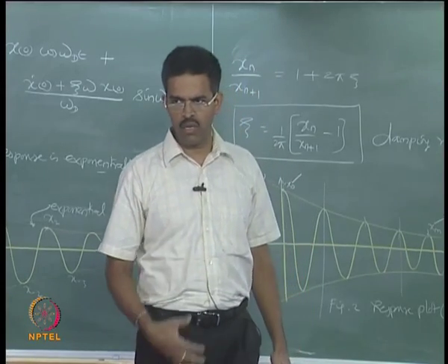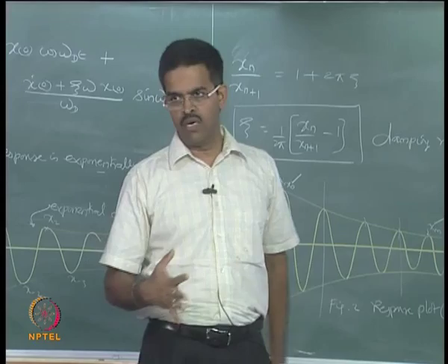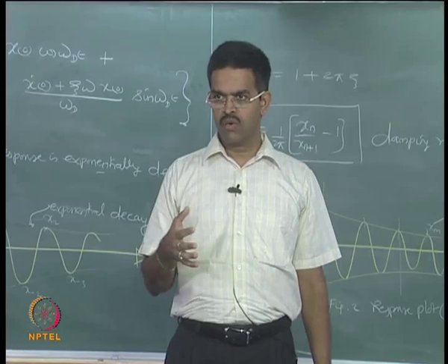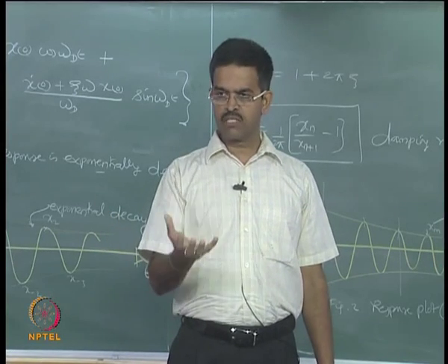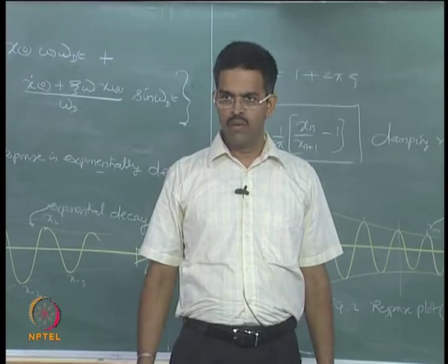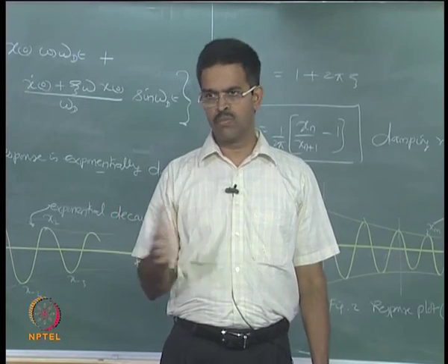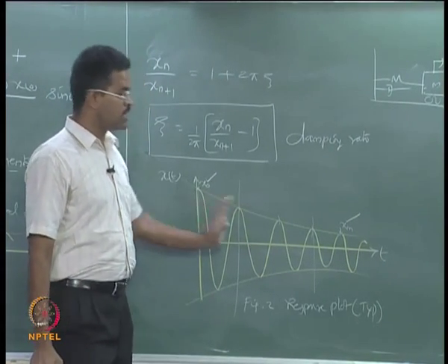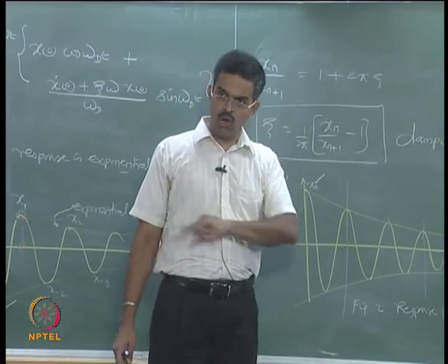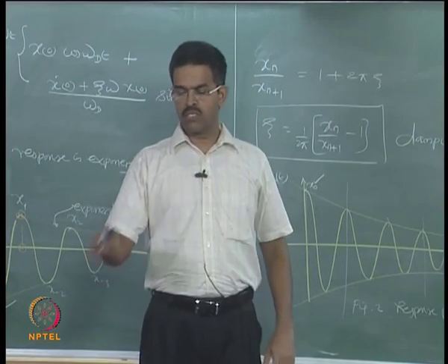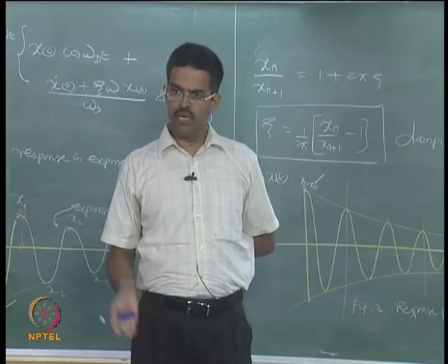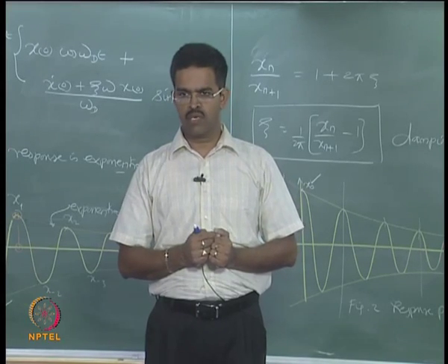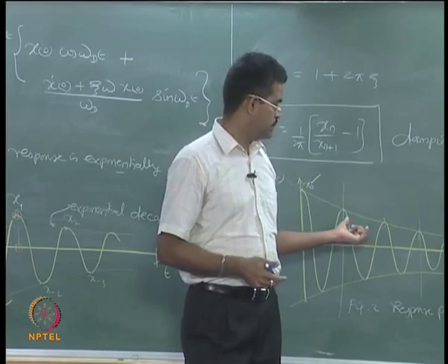for example maybe a TLP or a spar or a gravity platform or an articulated tower, commission it, do not apply any excitation force from the wave or anything, let the structure remain static at t is equal to 0, apply a free body motion to the mass point and get the response plot. From the response plot you can find the damping imposed on the model by water surrounding the body, material deterioration, all put together. Okay. This is how we can easily obtain the free vibration response,